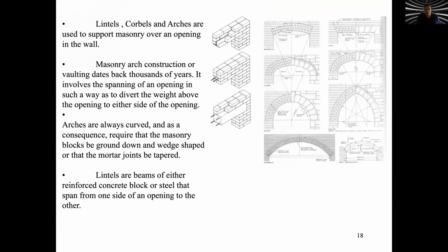When we have masonry walls, we need to understand that one of the challenges is to make openings in the walls, because masonry walls usually support their own weight and the weight of the roof system or other floors on top, and making openings makes the wall not as strong. Therefore, we need to look for ways to make those openings.